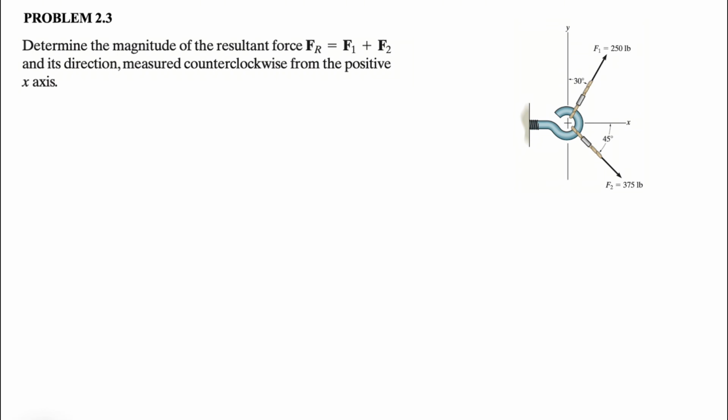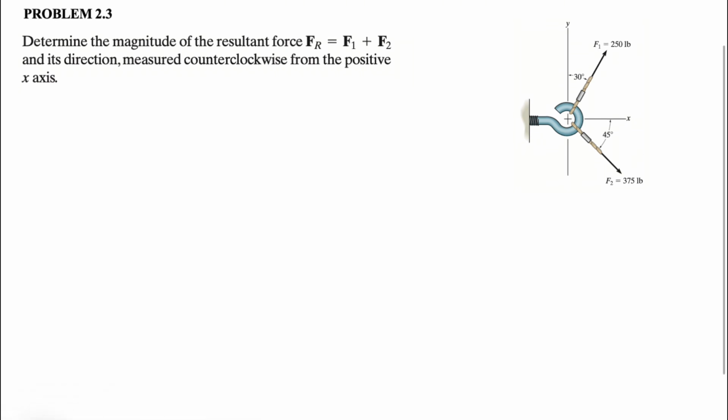If you do that, we're going to draw a line parallel to each of these two forces. So one parallel to F1 and another one parallel to F2. And the line that connects the origin to here is going to be our FR. So now we can use the law of sines and cosines in one of these two triangles that we have. We can go with the top one. I'm going to highlight it in yellow.